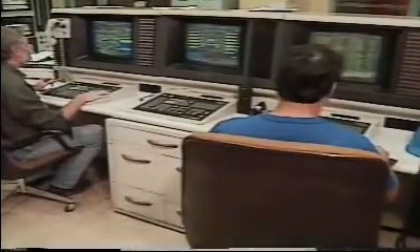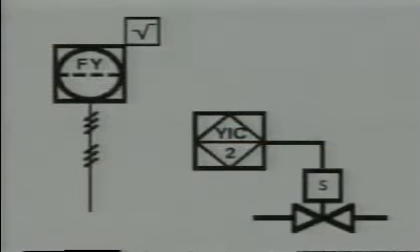If Y is the first letter, it represents controls that are event-driven, such as on this valve. Y might also signify a state or presence. As the output function, Y indicates compute or convert, such as this square root extractor.